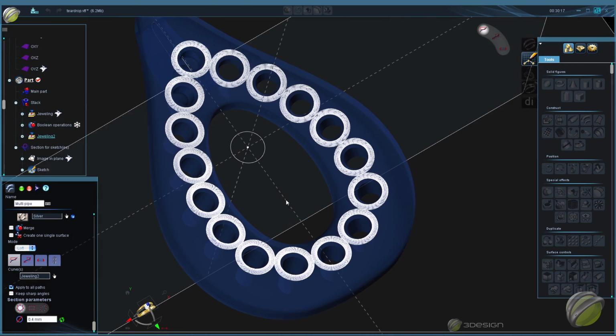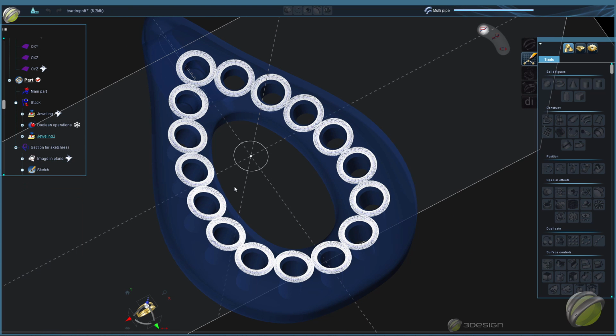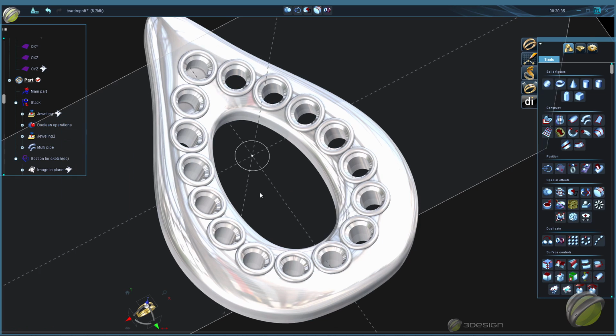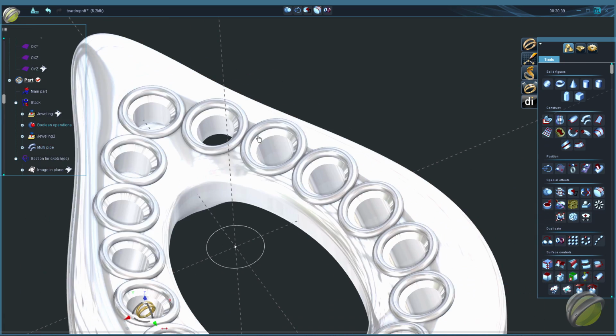We'll have to keep an eye on that when we do our Boolean. Might have to make them a little bit smaller or make them overlap more so we don't have those shared surfaces between them. We also have the edge around the stone that could become a shared surface. So let's look closely here and see how we have this set up. I think we're good on the inside.